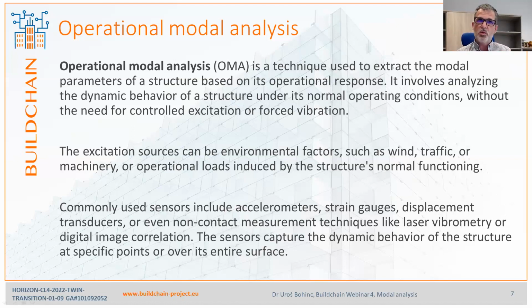So there is always some dynamic response. It's only the fact that this response is usually very minute, and it's hard to detect. So you have to use highly sensitive instrumentation. Normally, these are accelerometers, or even strain gauges can be used, displacement transducers, and so on. So you have to take care of the measurements, which have to be done really precisely.